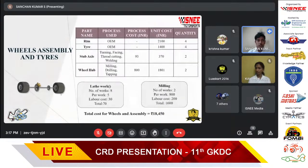While considering the wheels and assembly, rims and tires are the OEM parts which we use in our kart, with a quantity of 4. The cost for the rim is 2,100, and the tire is 1,400. The stub axle, which is used to assemble the front tires, is processed by turning, facing, thread cutting, and welding. The process cost is around 93 rupees, and the unit cost for a stub axle is 3,370 rupees.